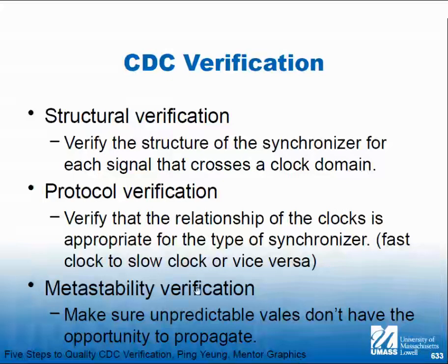And then metastable verification. Even when you put a metastable filter in, even when you put the dual rank flip-flop in, there's a chance that the metastable state could still go through. So what you want to do in addition is have logic design techniques such that a metastable state wouldn't cause damage, or it would limit the damage. As an example, if I have a state machine that has 6 states, but I have to code that state machine into 3 bits, right?